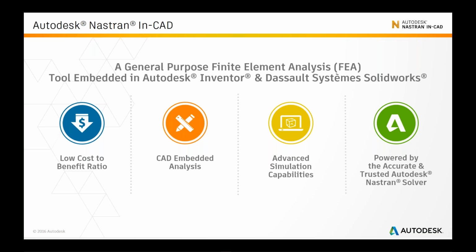So it not only is powered by the trusted Autodesk Nastran solver, but it comes with all advanced simulation capabilities. Now, many of the CAD embedded solutions have just very basic functionality like linear static or modal analysis, but this can go up to non-linear or solving transient types of analysis, or complex solutions like a drop test.